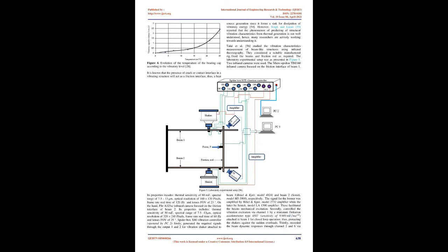Singh et al. [27] carried out analysis of ball bearings under dynamic loading, using IRT, and observed an increasing temperature trend for the bearing under an abrasion state. Mahmoud et al. [28] investigated the usage of IRT for detection of rolling bearing degradation and observed that a rise in temperature could be correlated with the level of vibration. Kim et al. [29] studied the fault diagnosis of ball bearings within rotational machines using the IRT method. The findings indicated that the method was well adapted for the monitoring and prognosis of bearing faults by qualitatively and quantitatively evaluating the temperature characteristics, according to the condition of the bearing.